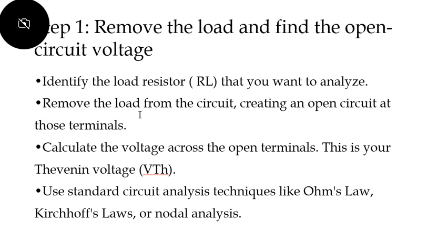There is a step-by-step procedure to draw the Thevenin's equivalent circuit. The first step is to remove the load and find the open circuit voltage. How to remove the load? The load means the resistor across which we need to find the value of current or voltage. So you have to identify the load resistor that you want to analyze.